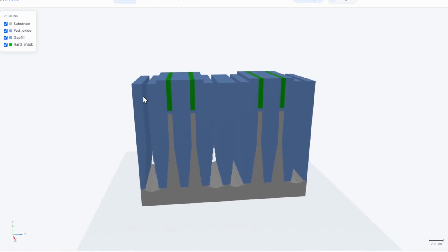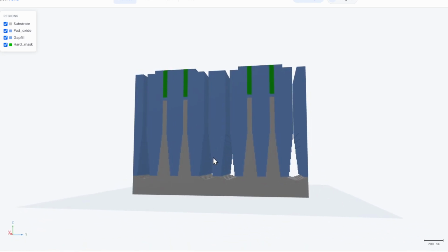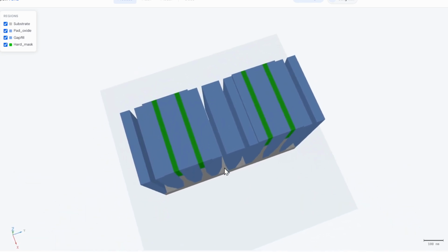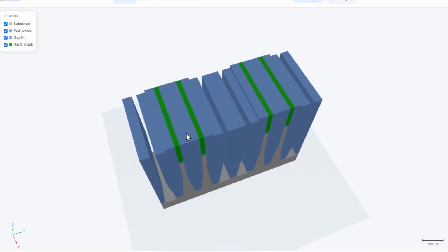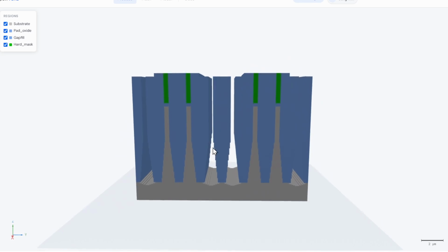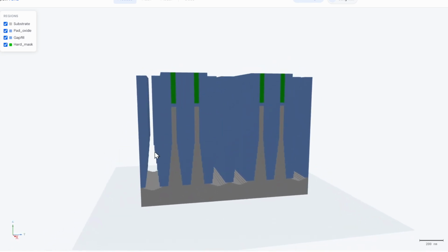Now, by etching the silicon only, we can completely remove the fin in non-active regions. So here we have active regions which are protected by our hard mask, and here we previously had fins, but they are now etched away.